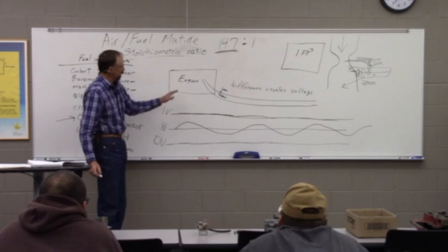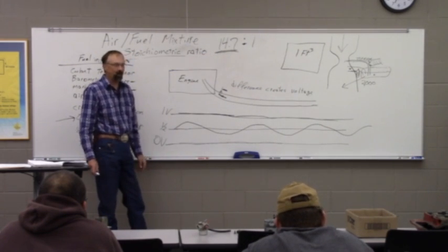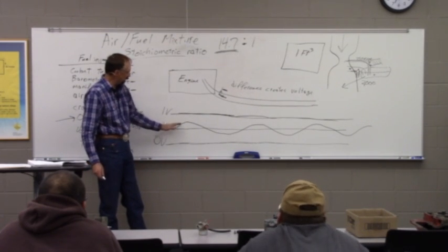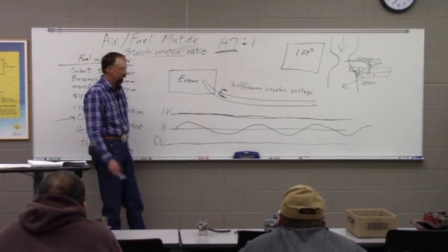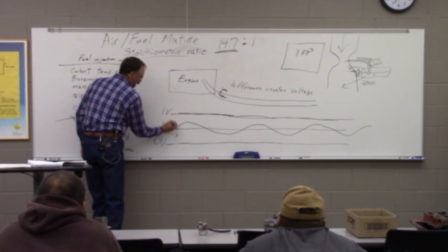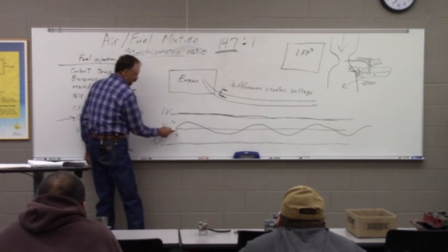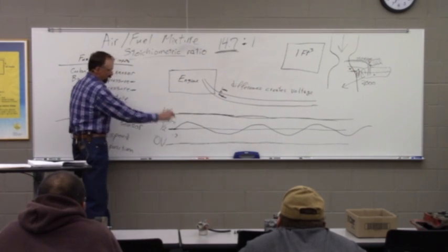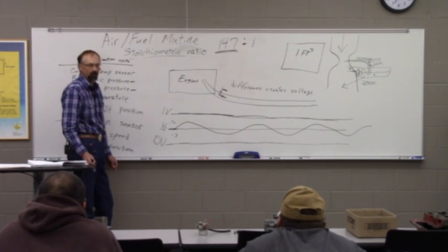But in one that we're getting real close to that, and there again, boy, you almost never can hit it exactly perfect. But if you're real close to that and things are all working right, it'll just dance back and forth between, I'm going to say somewhere in that 0.3 volts to 0.7. It'll never hit 1, it'll never hit 0. It just dances right there in the middle, and it'll dance back and forth across this half volt line, and there'll be a lot of cross counts per minute.